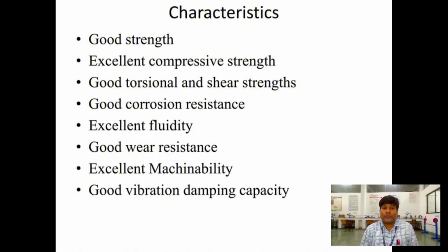It also has excellent fluidity. Good wear resistance because it is a hard material. Excellent machinability. It means you can machine it easily using different kinds of machines. Good vibration damping capacity, so it is also used in automobiles like bikes, cars, etc.